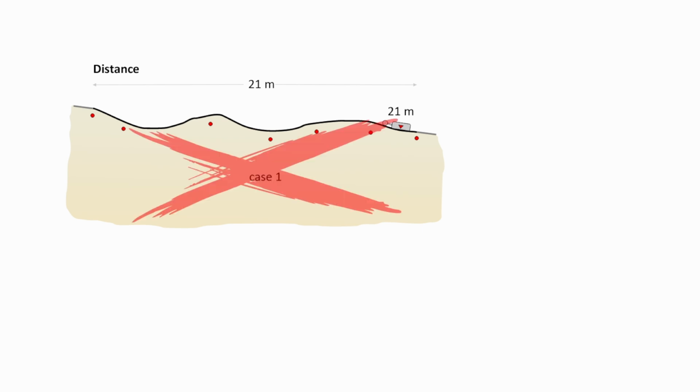The dimensions of our area are 10 by 21 meters, so the length of the profiles will be 21 meters. We're starting the data acquisition using a measuring wheel, and we'll wrap up at the point where the measured distance with the wheel is 21 meters, right? Well, not exactly. To be honest, I couldn't believe that someone would trust a measurement wheel to that extent. Essentially, a measuring wheel can provide reasonably accurate results only for short measurements taken on flat surfaces, like asphalt roads. Longer stretches will also carry some error, but we'll discuss that in future episodes.